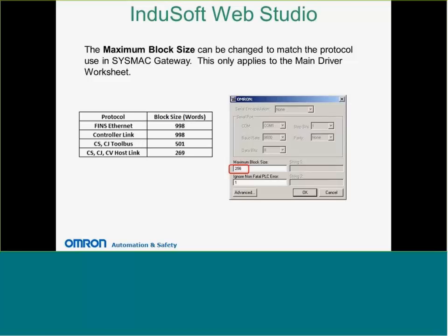The second thing we can do is set the block size. The block size has to do with the main driver worksheet and how InduSoft Web Studio optimizes communications by making virtual read groups. I know there are some additional InduSoft videos on the topic of driver worksheets, so if you want to know the details of how all that works in the background, you can do some research and watch one of the videos.